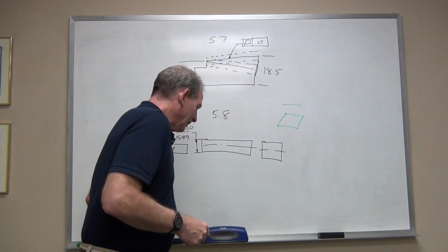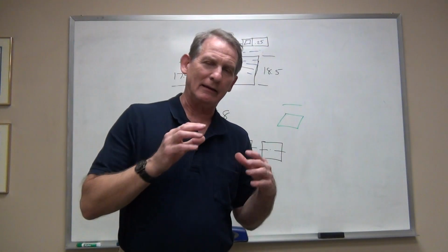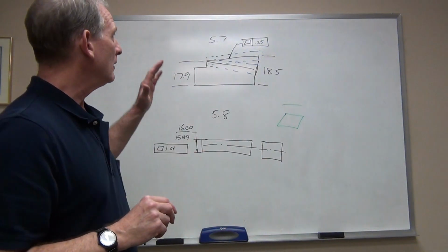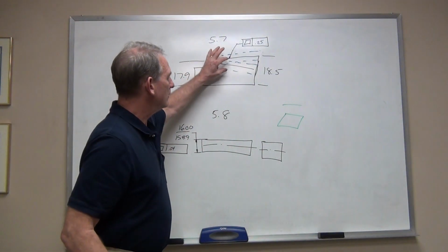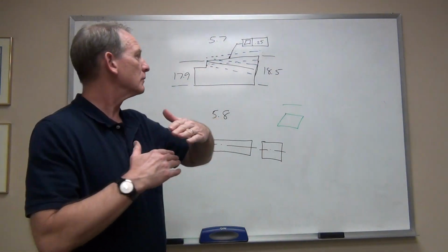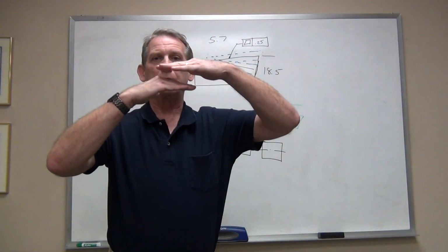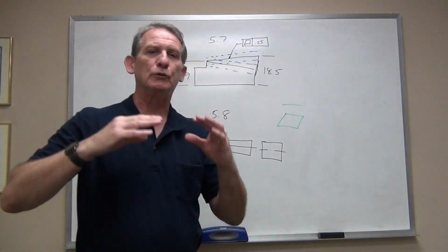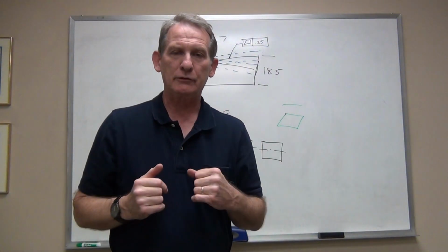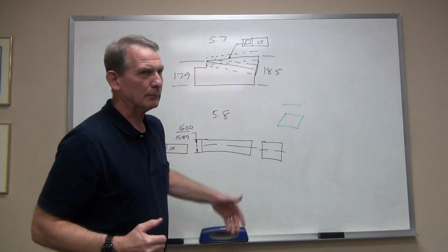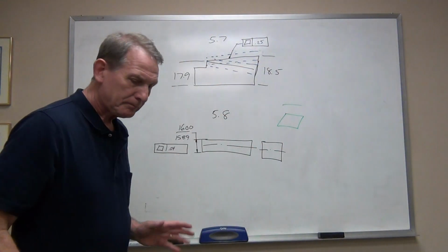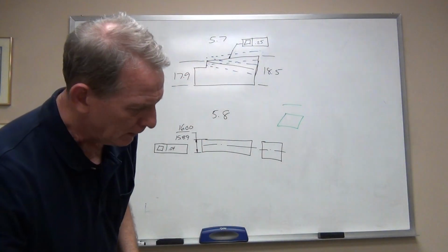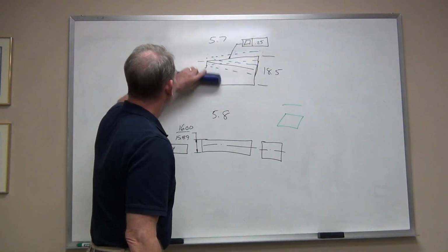Now again, that is easy to say mathematically, and on a surface plate it's not as easy to do perhaps, but there are techniques to do it. The important thing is that the tolerance zone is two parallel planes, 250 thousandths apart, and they can be tipped, they can be rotated, they can do whatever they have to do to envelop or encompass that surface, no matter whether it's actually tipped in reality or not. Okay, so surface element, two derived or two parallel planes as the tolerance zone.